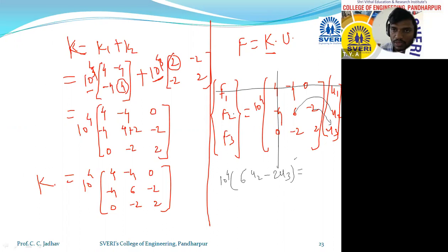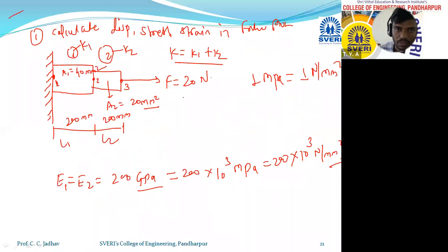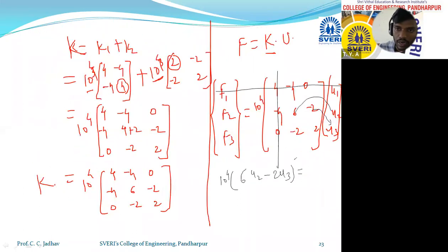in front of this, see here, there is f1, f2, f3. Now f1 means the force here. What will be the force value here? 0, because this is fixed. The force value at this point will be 0. The force value here is whatever you have applied. So at the time of entering this f2 value in front of this equation, that will be 0.